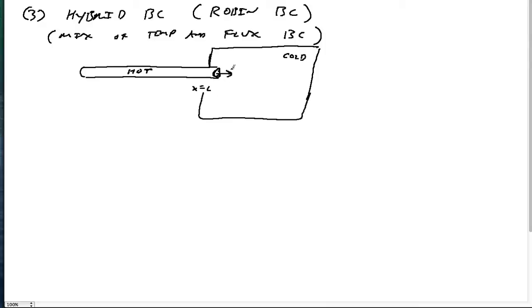And so again, we're going to have some heat flux coming out of this end. But it's sort of going to heat up the air. If we think of this as a fluid, like air, it's going to heat up the air right around there. And that's theoretically going to slow the transfer of heat, because the air right around the bar end will be heated up.